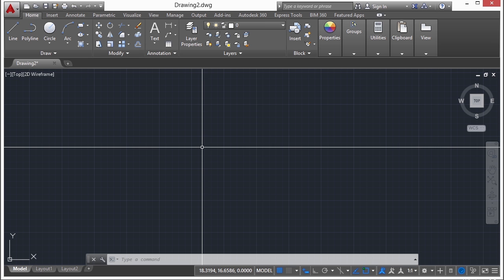Styles control everything in AutoCAD. Text styles are no different. They are actually very simple to create and edit, and probably one of the easiest styles in AutoCAD to use. Now, you can just open up any regular blank template file, or if you have another file already open, that's fine. To get to text styles, you just type in the word style